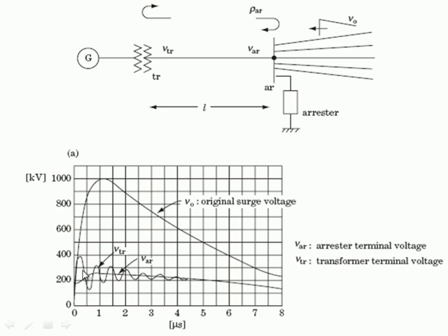Now, this is transformer terminal voltage. Now, see this one now. See this surge. Surge is this rise, sharp rise. Now, see the operating terminal voltage here. It is touching 400, which is 380 suppose. Now, if it would not have been in the system, a lightning arrestor, what was going to happen? There was a rise in voltage that was about 1000 kV, while your operating voltage was less than 400 kV.